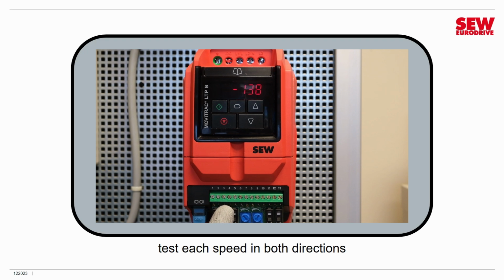The last thing we have to do is check the stop ramps. Now, just a reminder before we test the ramps, remember we've set the slow ramp, which is standard deceleration, to 4 seconds and the fast ramp to 2 seconds. Now remember, those are for 1500 RPM speed changes. Since we're only doing 1000 RPM speed change, they will actually not take that long. The slow ramp will take about 2.6 seconds and the fast ramp about 1.3. We'll time that just to see if it comes close.